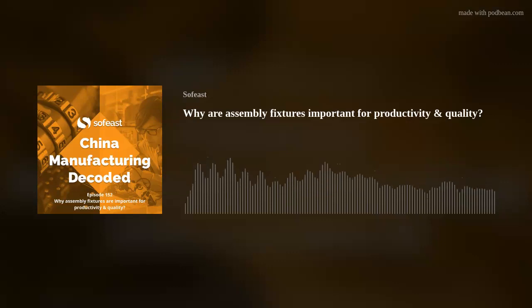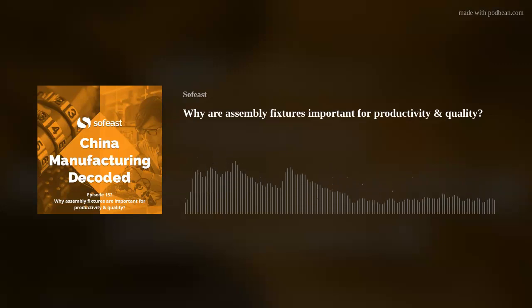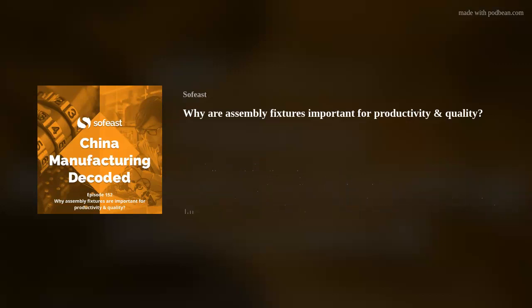So we don't have to actually test live, in other words, with water, but it's a critical stage within the assembly itself. So that will be a very quick checking fixture where you plug in one end of the hose, plug in the other end, turn the lever, you've got air. Yes, it's holding pressure. Unplug. It's safe to assemble. We know we're good to go.